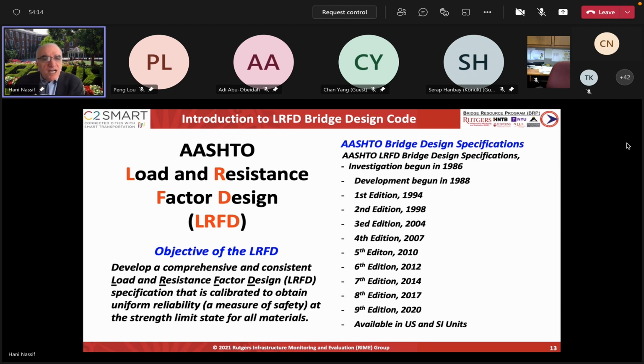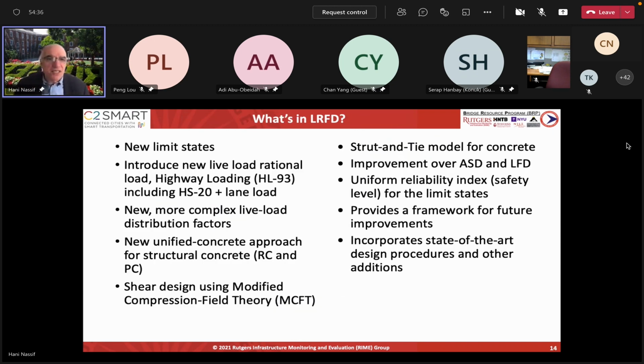If you use the program, it's called Response 2000. It's a very, very nice program. It's free. It's on the website in Toronto. You can download it. You can get the exact capacity. However, if you use the design procedure that Professor Collins developed the first time, there were some kinks in it. And you will see in the code today how we adjusted that.